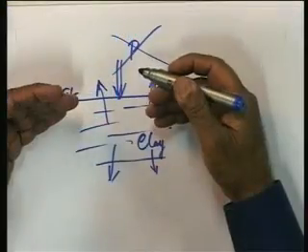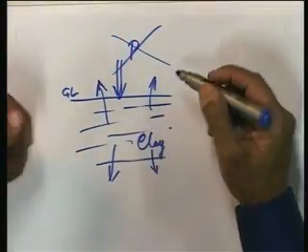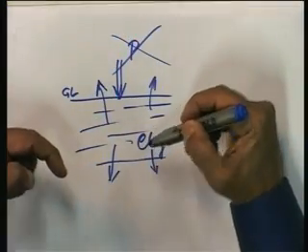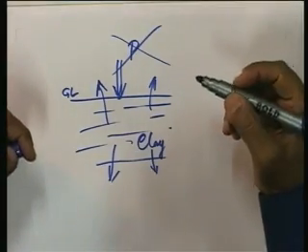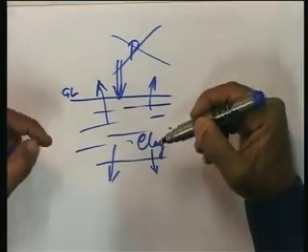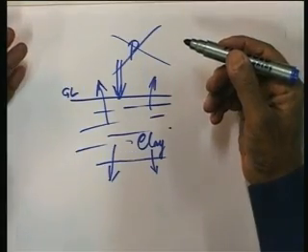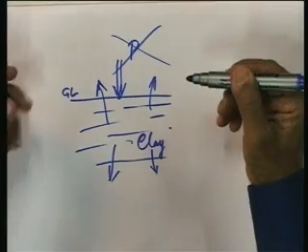Therefore, initially when the load is applied, it goes straight into the water, and then the water experiences pressures which are more than the hydrostatic pressures which it was experiencing before the load was applied. And this is the fundamental idea that helps us to compute how and at what rate the settlement should take place. Now, see, we have two states, one is without load, another is with load.